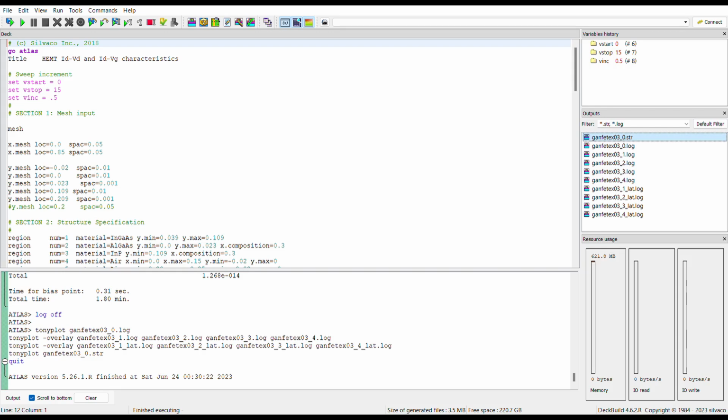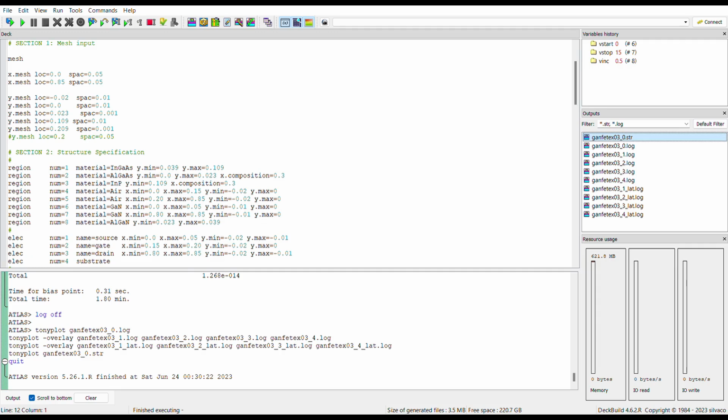Now I am going to explain our final work. As Rupak mentioned, there are some problems in our previous structure because of which we cannot achieve our goal regarding bandgap curve and breakdown voltage. So we have introduced aluminum gallium arsenide layer as a spacer layer, indium gallium arsenide as a channel layer, and gallium nitride as a cap layer below the electrodes.